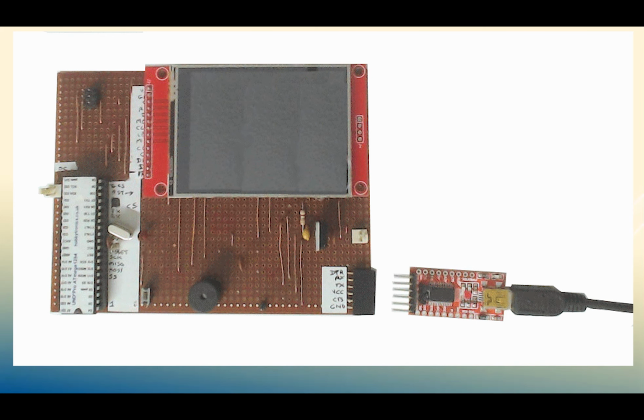This is something that I'm still working my way through. It's using a larger Arduino chip than the 328. And it's going to hopefully be a touchscreen version of the EasyBus controller. But to program it, I've had to use, as you see here, the 232 serial adapter. USB coming in from the right-hand side plugs into my board, and it's taken from there to the chip itself to program it. So it depends whether you're going to program through the USB or through the serial connection.